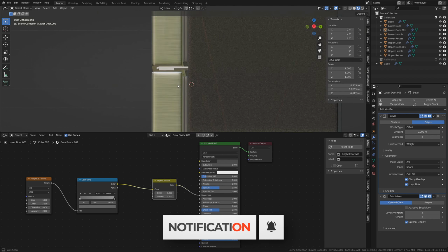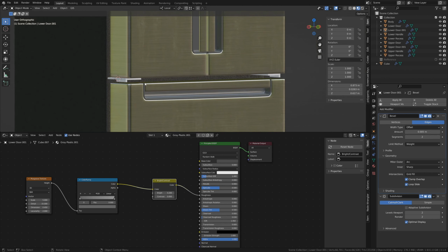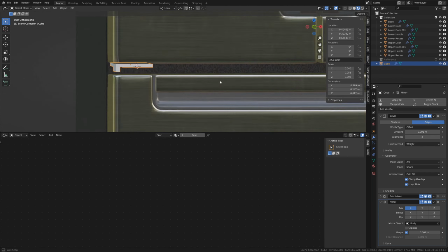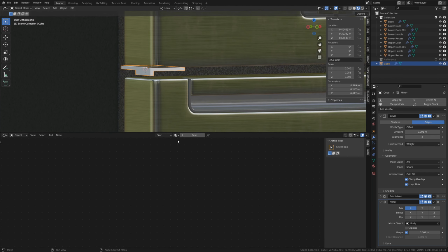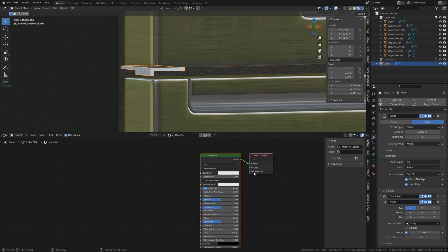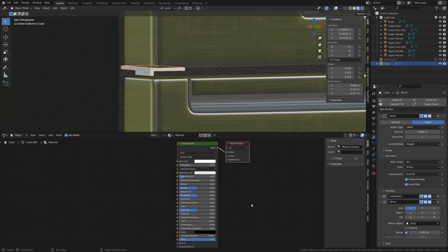One thing that we have not imported a material for are these hinges. They are actually kind of a chrome look in all the pictures I've looked at. So let's create a new material. This will be very quick, very easy. This can be all white if you want it to be perfectly chrome. Turn metallic all the way up and turn the roughness all the way down. 0.1 is probably something a little more realistic.